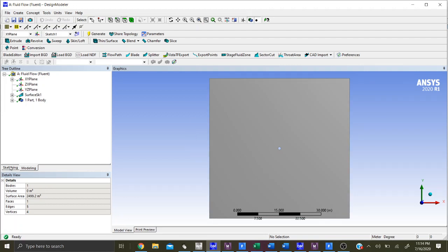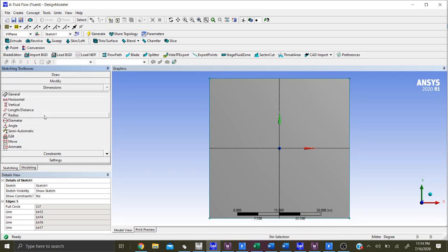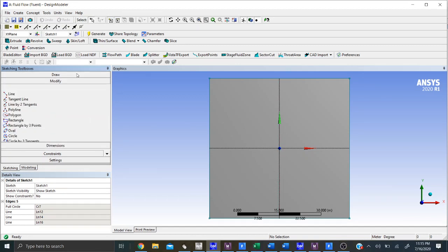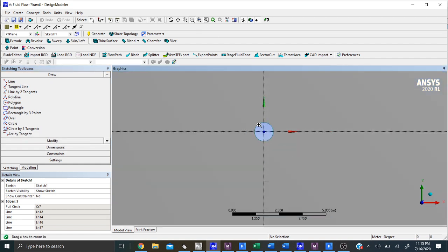In order to do that, we go to Sketch, start by sketching the circle, going to Dimensions, and making sure that the circle dimension is a diameter of 1 meter. So let's zoom in to the circle. There's my circle. From there, after creating the circle, I took the line tool and drew 2 lines out horizontally from this point.